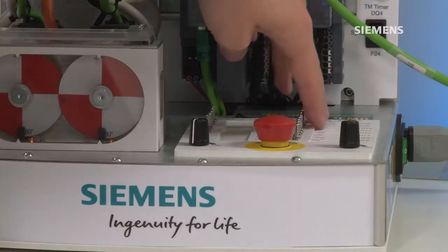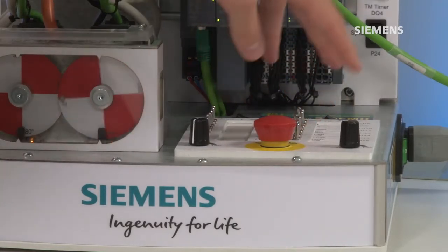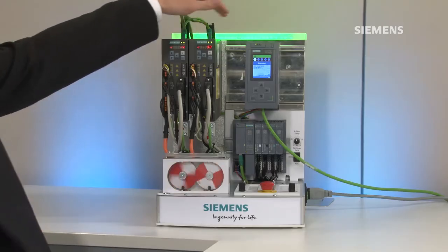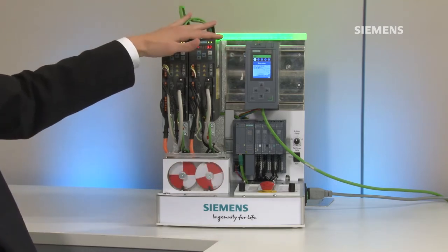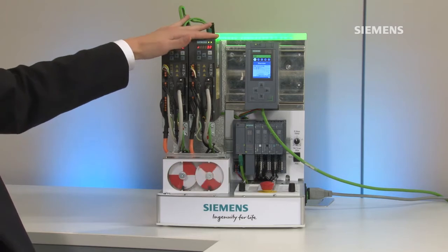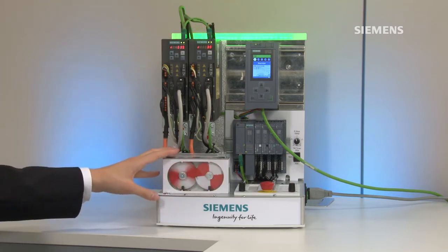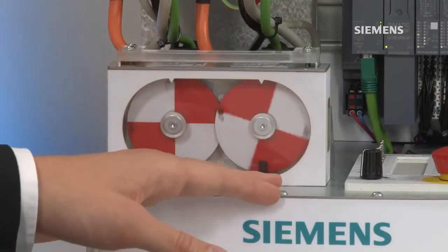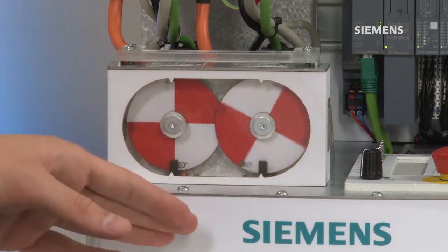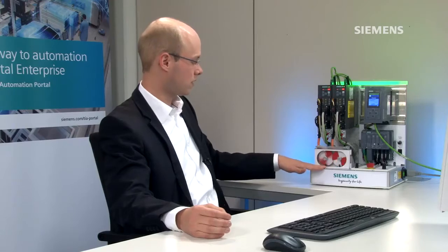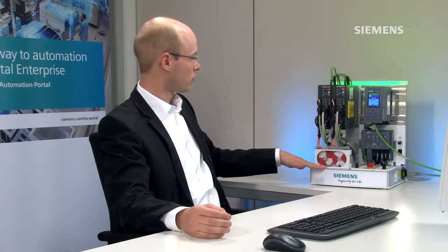Let's take a closer look at the setup. To do this, I'll first switch on both axes. We can see two motors, each driven by a SINAMICS V90 servo drive. And the higher-level S7-1500 technology CPU actuates the drives, providing the movement commands and coordinating and synchronizing both axes. The right axis moves continuously, and the left moves in relation to the right axis, sometimes to the right, sometimes to the left, then back to the right, and so on. This is coordinated by the SIMATIC.